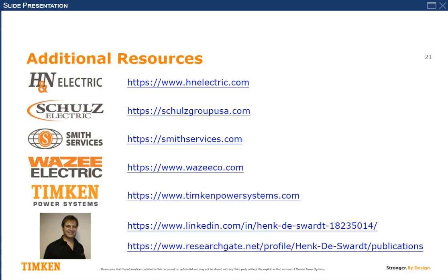The other thing you also look at is two different things. One is hotspots. In other words, as you energize the core, you take a thermal camera and you scan the core for a 10 degree increase in temperature in a specific spot. That's called a hotspot. In other words, there's local, specific damage to the insulation. Now, the core losses might still be low because it's a whole core, but in that spot, because the lamination is damaged, the core gets hot.